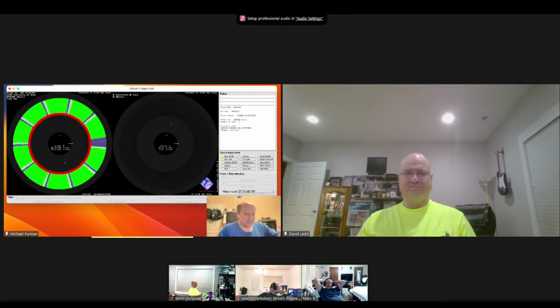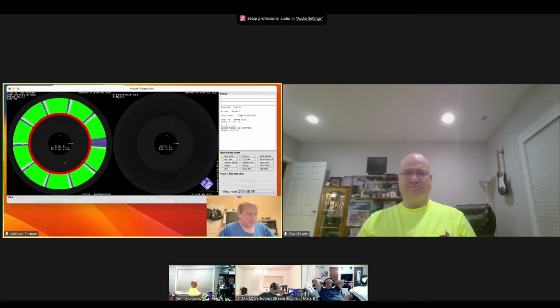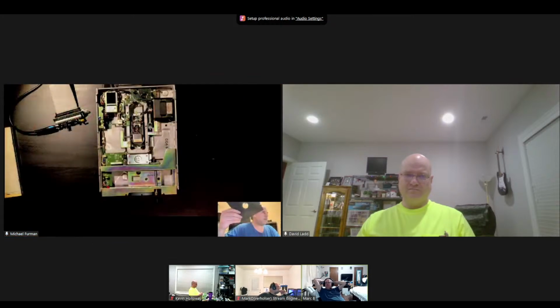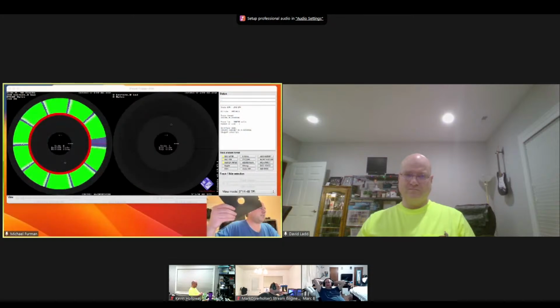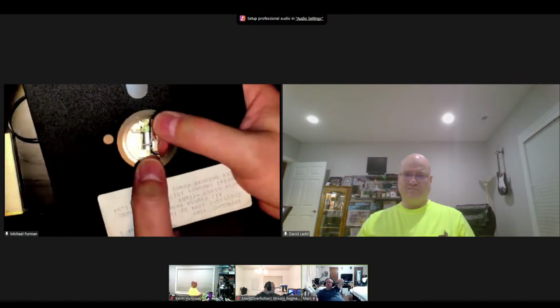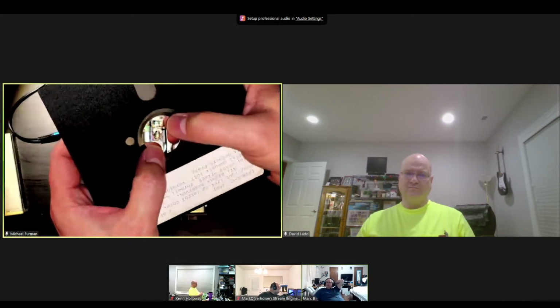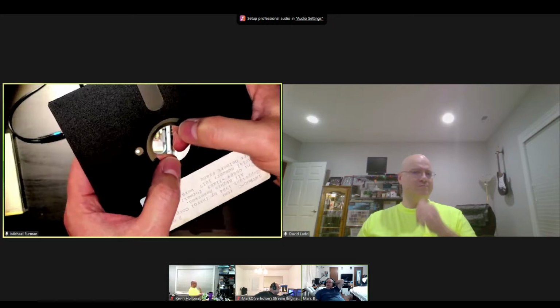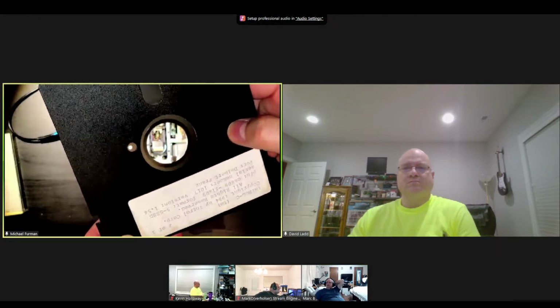As the disk goes around, every disk has an index hole, and there's an index sensor that detects it. Here I've already imaged this disk, so I can literally show you. If I switch to the first disk, it didn't have one that big. It had the little ones between the sectors. If I gently turn this disk around, eventually, there we go. See that hole there? That's the index hole.